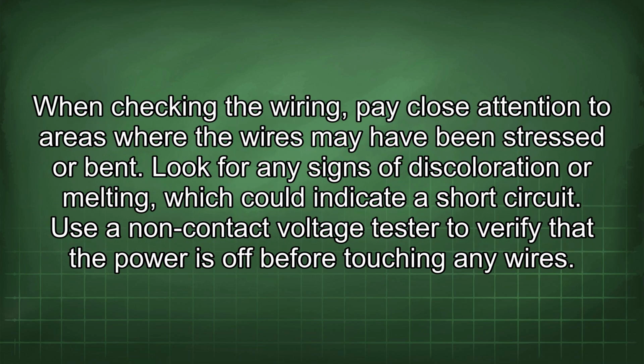When checking the wiring, pay close attention to areas where the wires may have been stressed or bent. Look for any signs of discoloration or melting, which could indicate a short circuit. Use a non-contact voltage tester to verify that the power is off before touching any wires.